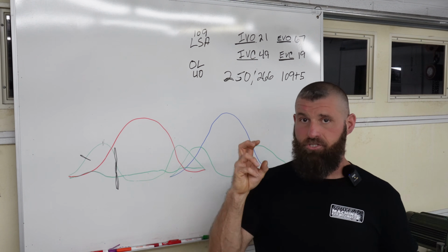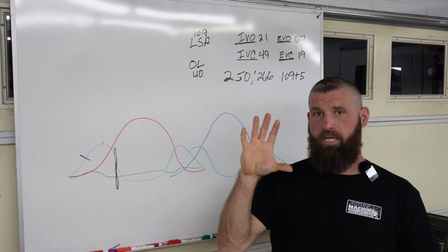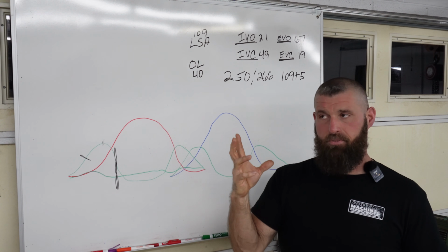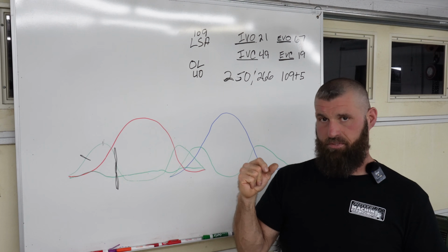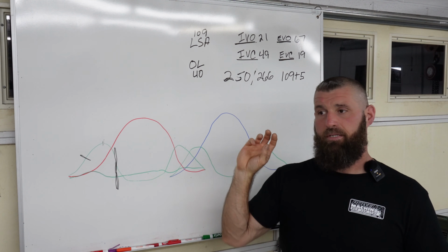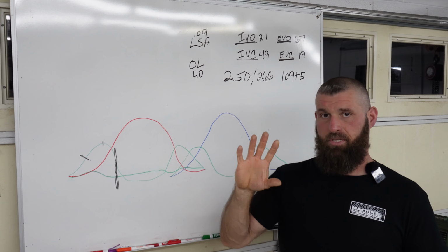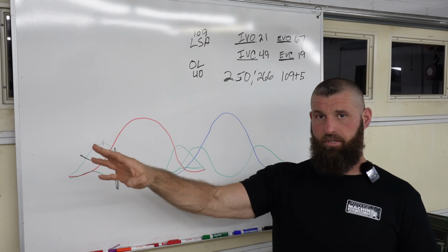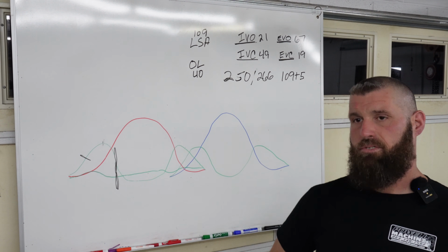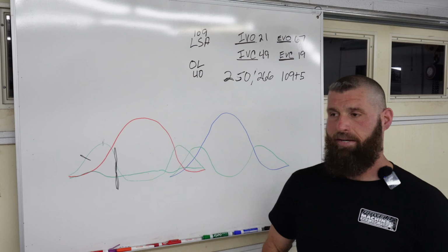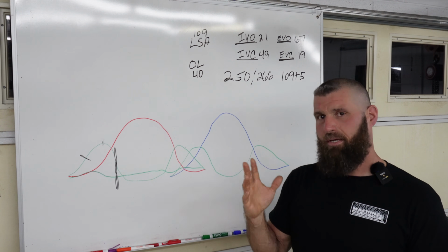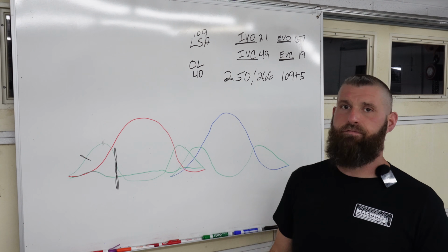Right? So that's the problem, is we can't really calculate it. Some people say they can, but I haven't seen it play out in real life. It's hard to calculate volumetric efficiency without the motor ever running. Just on paper, you just about can't calculate it. So I don't get too broke down on dynamic. It's something good to look at. It's a basic tool, but I see varied results.